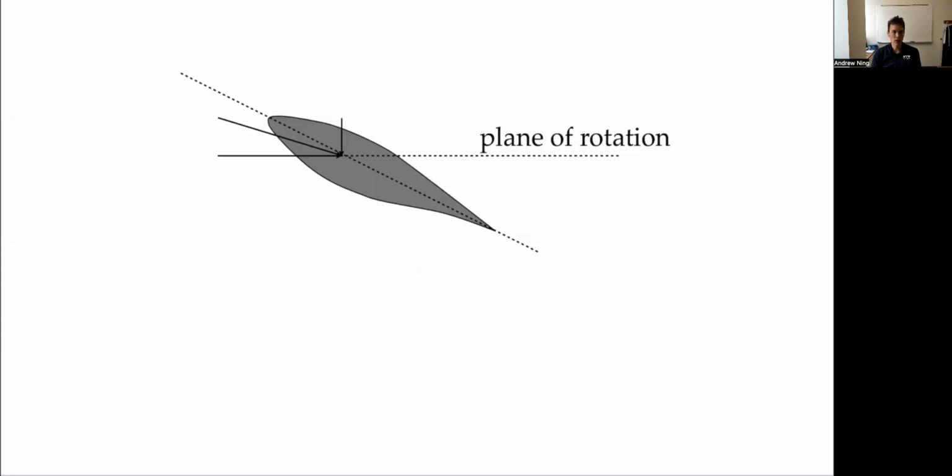So let's look at a cross-section of the blade. It always takes a little bit of time to orient yourself the first time you look at these. Let's imagine that the hub of my propeller is into the page, so I'm looking towards the tip, or I've cut a slice of my blade. So I'm looking at a cross section and it's rotating. Let me draw something here. This velocity vector here would be v infinity. So this would be spinning around kind of like this. Velocity is coming this way. If I'm a propeller, that means I'm on a plane, I'd be flying up this way.